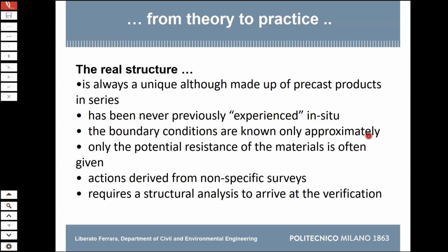As I was saying Monday, a structural designer cannot say, oh, I'm using this beam, and this beam, according to what the factory says, has this load-bearing capacity. Yeah, that is information that he uses, but he's responsible then to check that that beam in that structure is subjected to certain bending moments, shear forces, and so on that comply with that. So the structure is unique, and you can test it up to some serviceability level, but you don't know what is its actual margin.